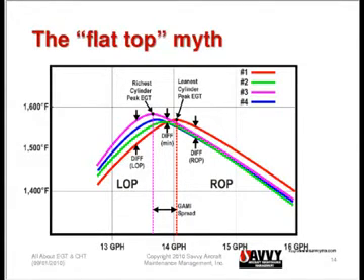The only way we can find GAMI spread is to run what's called a GAMI lean test, where we simply start with a rich mixture and gradually lean it, and note the fuel flow at which each cylinder peaks. The difference between this fuel flow, which looks like about 14.1 gallons an hour, and this fuel flow, which looks like about 13.6 gallons an hour, is what's called a GAMI spread. And in this case, it looks like the GAMI spread is roughly a half a gallon an hour, which is